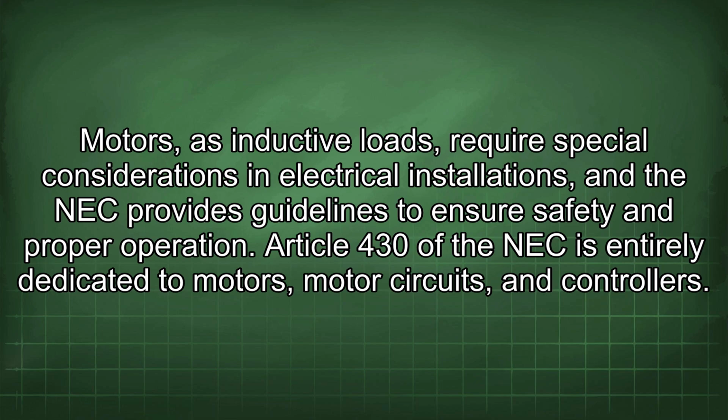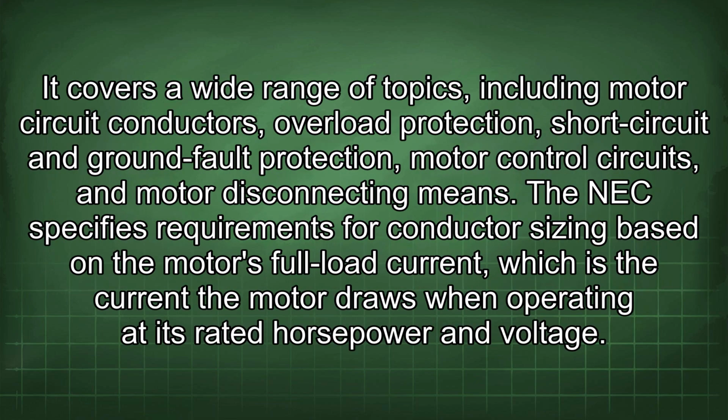Motors, as inductive loads, require special considerations in electrical installations, and the NEC provides guidelines to ensure safety and proper operation. Article 430 of the NEC is entirely dedicated to motors, motor circuits, and controllers. It covers a wide range of topics including motor circuit conductors, overload protection, short circuit and ground fault protection, motor control circuits, and motor disconnecting means.